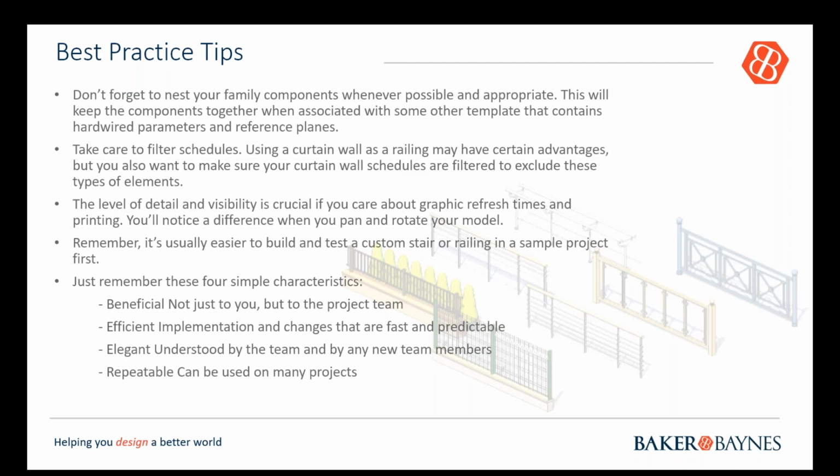You want to make sure that when you don't require that much detail, the detail level is set on coarse. And remember that it's easier to build and test a custom stair rail or railing in a sample project first. So don't just plonk your railing into your project. Try it out in a sample project, test it, see if it works. If it's good, bring it into your main project file, and then you can start using it.